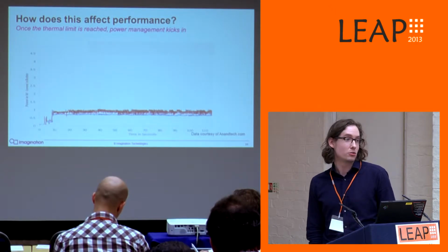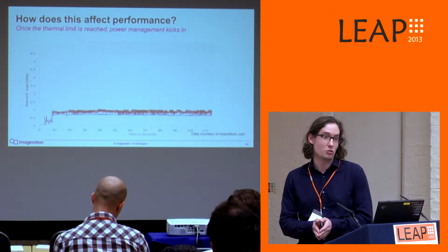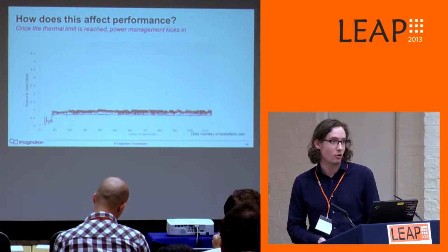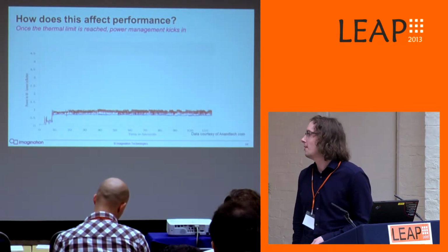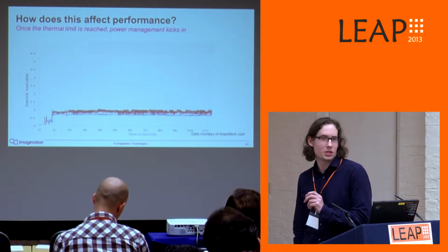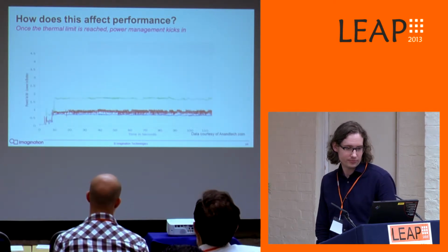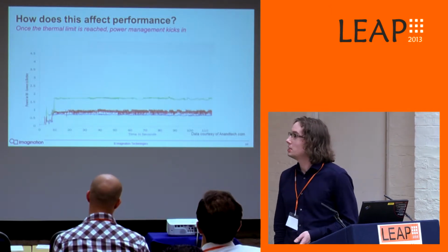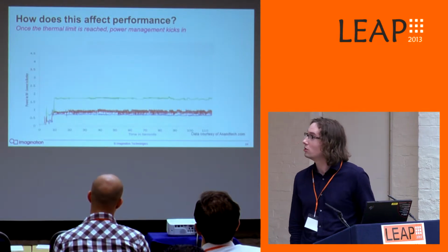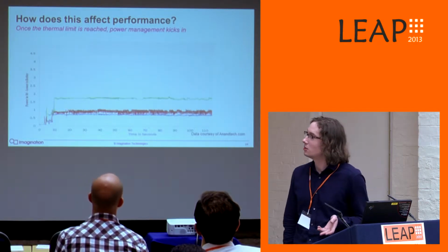Both of them are tile-based renderers. So in terms of graphics rendering, if you have a 3D scene, one of the things you can do is effectively use a tile-based renderer to reduce the amount of overdraw, and that generally improves the power. So a straight line is very good. The red line is pretty good, but the zigzag there represents a little bit of clock management that's going on. Then the green line, this is an immediate renderer, so there's a bit more overdraw here, so the actual total power is going to be a bit higher, but actually, it's still pretty good.